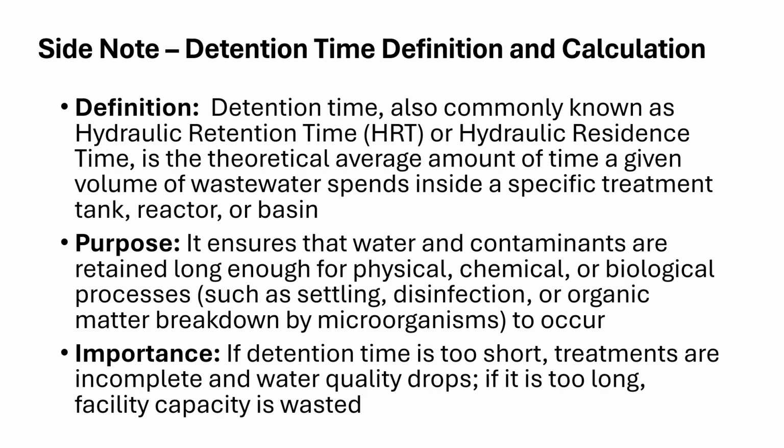The idea is that when we have a detention time, we want to meet that detention time to make sure that the water and its contaminants, its organic loads, settlable solids, what have you, are hanging out long enough for the settling or floating process to take place, or any other process we may be looking at.